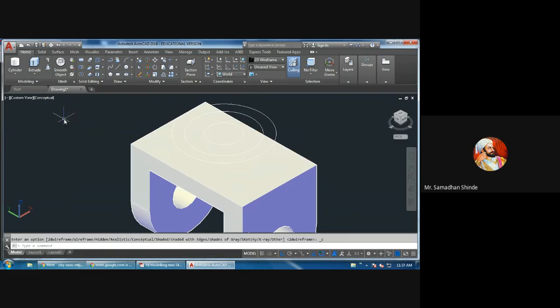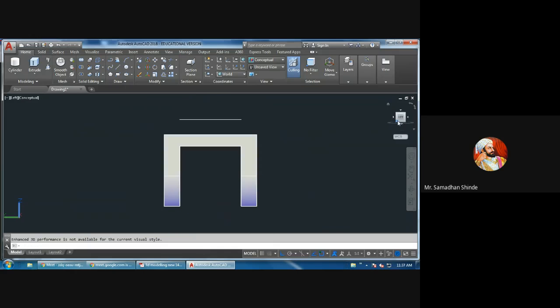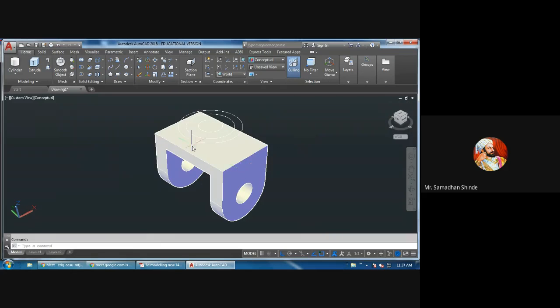What I have done is, see, these circles, if you see from the left hand side view, I have taken through 20 distance top, along vertical, because now I am going to extrude these circles up to this 20, so that it will form a cylinder. Okay, so extrude this circle, outside circle, enter through 20. It will form something like this.